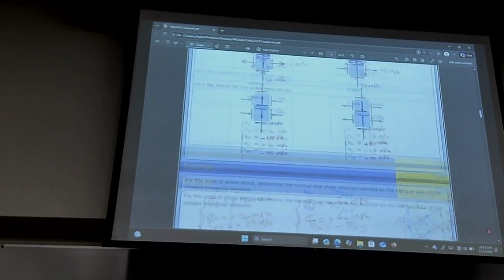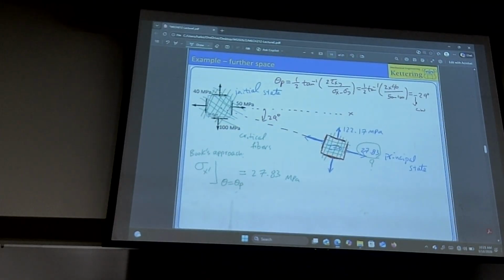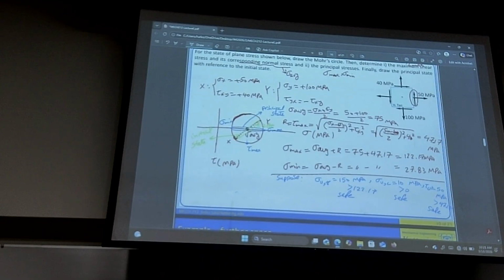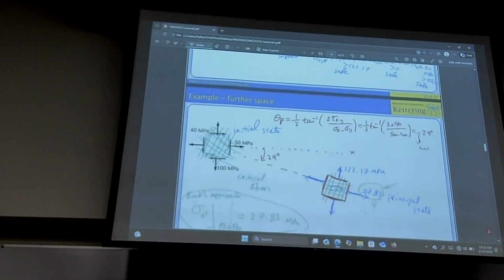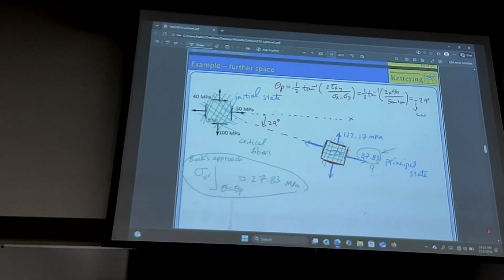All right, what was the lesson here? The textbook says, guys, if you want to come up with what value you have to put in here, you have to do this equation. I said, no, you don't have to. Much easier. Just look at this x. Whichever is closer to, whether sigma min or sigma max. If it's closer to sigma min, put sigma min on that side. As easy as that. You already did the work for that. So whether this or that, it doesn't matter in the test, either one works.